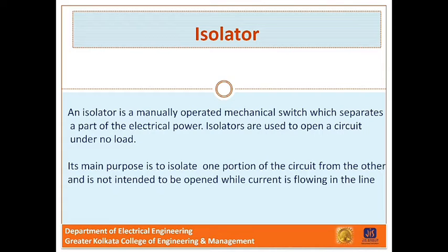Its main purpose is to isolate one portion of the circuit from the other and it is not intended to be opened while current is flowing in the line. Isolators are generally used on both ends of the breaker so that repair or replacement of the breaker can be done without any danger.